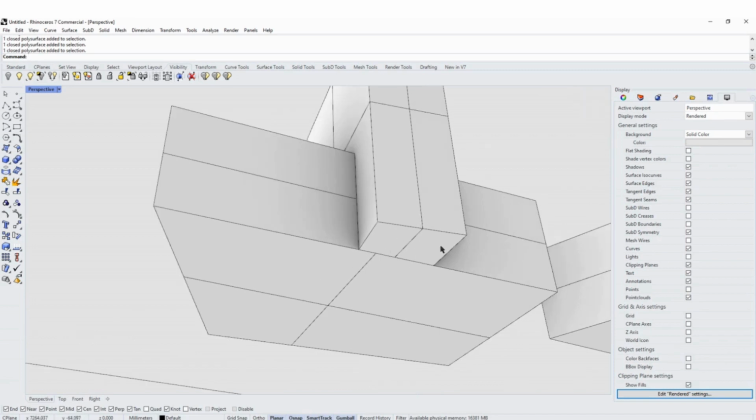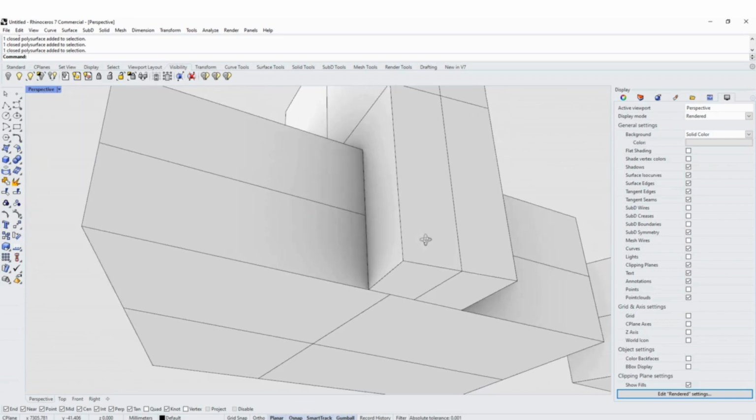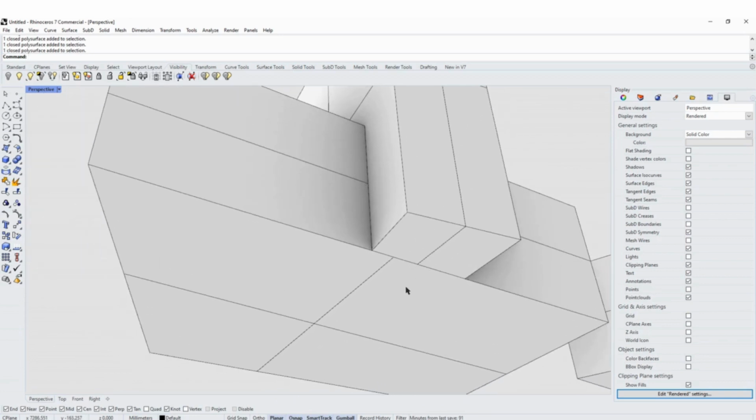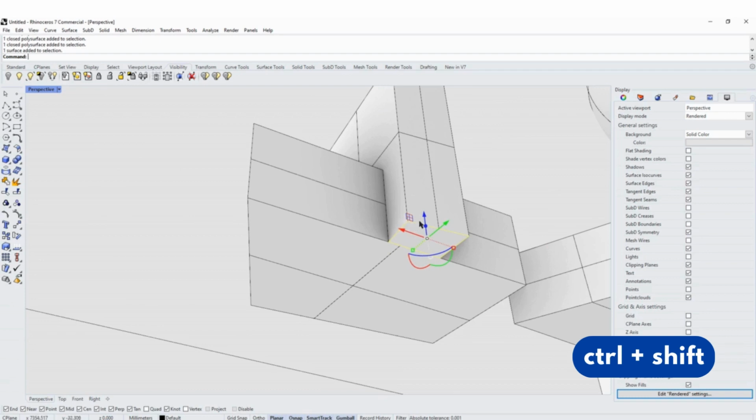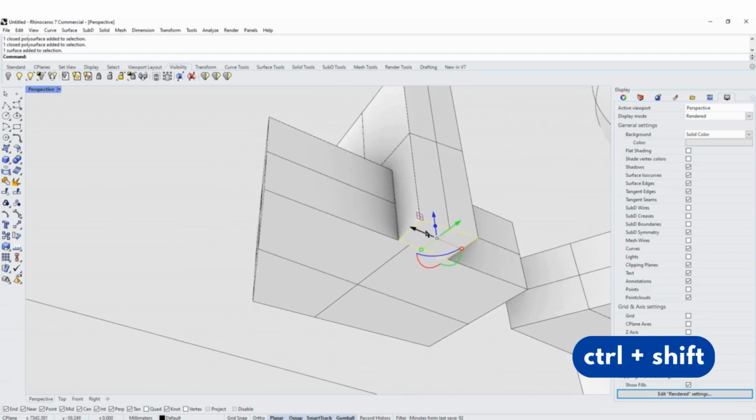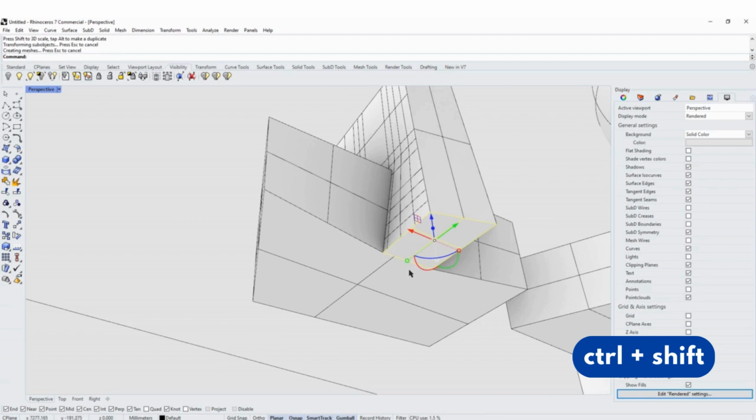But also you can select it. How you can select just this surface: go here, orbit to be just under the shape, and then press at the same time Shift and Control. Press them at the same time, and then simply click on the surface. And now you can see that from this whole shape, the only thing we selected right now is just the surface. As we did with the control points, the same way you can go and scale just this surface.